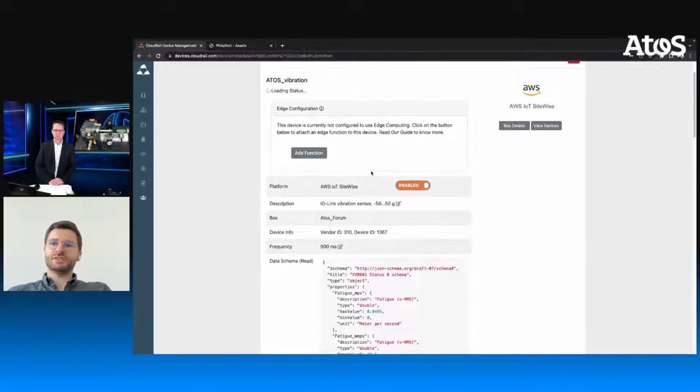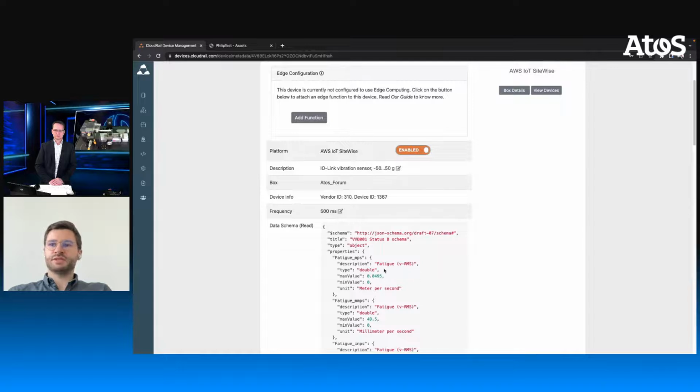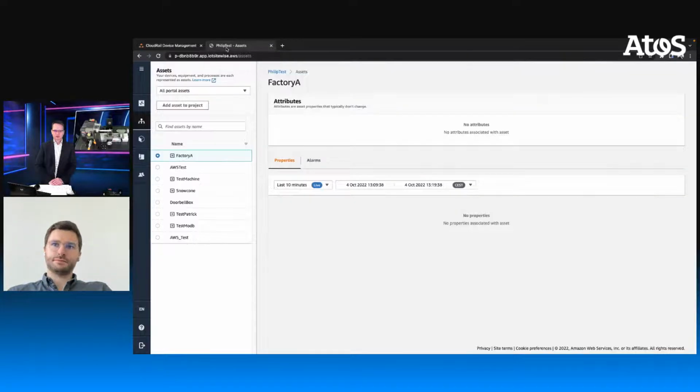So what you can see here is a very clear JSON format. You have this value, for example, velocity on the x-axis, double type value, unit is meter per second, min max is defined. So we have a very, very clear data sheet. You don't have to care, if you use this solution, how the sensor measures. You just use the data as it's sent to the cloud account. And there are numerous freewares out there which can interpret that data. So really very easy and straightforward.